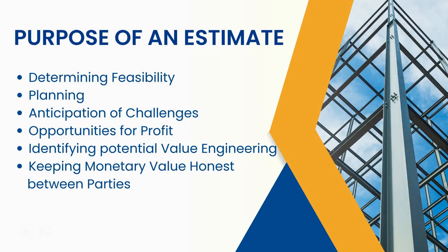Is the volume of the work designed and expected going to be able to be built with the budget that we have? So determining feasibility up front is extremely important because this allows us to put other mechanisms in place if we find that we don't have enough money. So that's when we can do things like value engineering, or we can identify alternates, or any alternate projects that we might be able to pull out for credits at the last minute before we go to bid on this particular project.